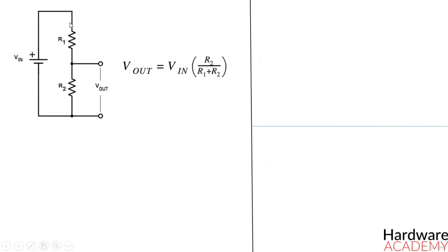We can calculate the theoretical behavior of a low-pass filter by using a frequency-dependent version of a typical voltage divider calculation. The output of a resistive voltage divider is shown here. If you don't remember this equation, please check the voltage divider course that can be found in the first chapter.